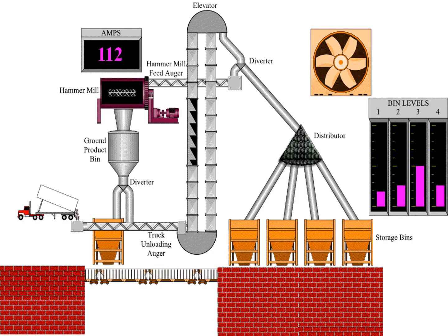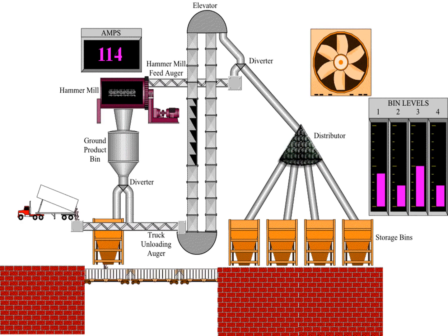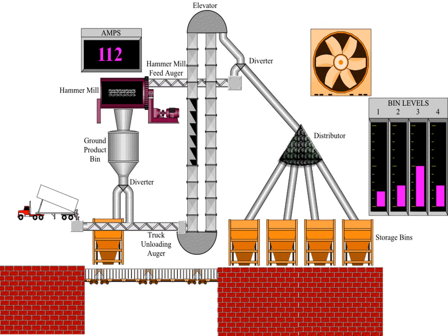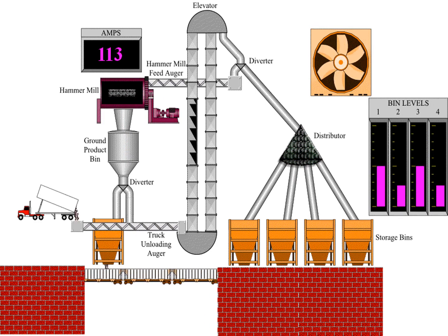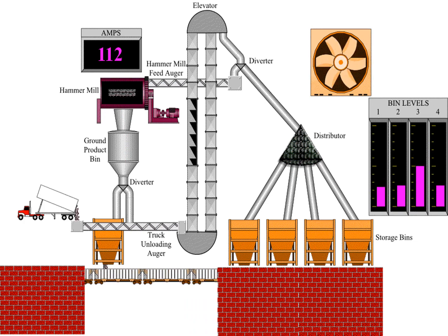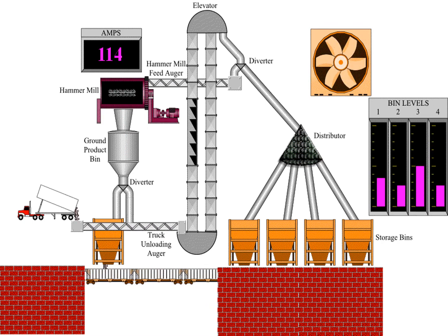This is the detailed diagram of a pneumatic conveying system. The pneumatic conveying system needs a source of air blowing or suction, means of feeding the product into the conveyor, ducts and cyclone or receiving hopper for collection of product. The product is conveyed by using air pressures greater than atmospheric pressure. The most common type of feeder used in this system is the rotary feeder.